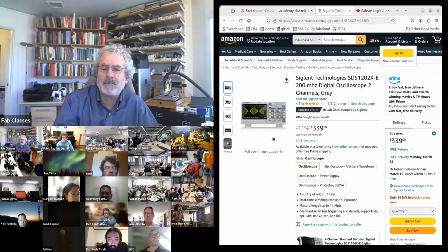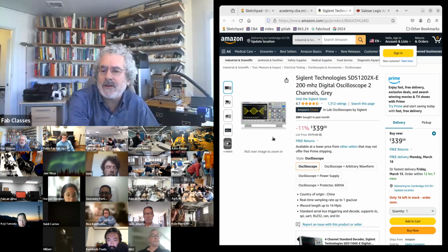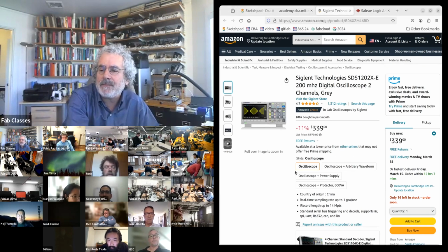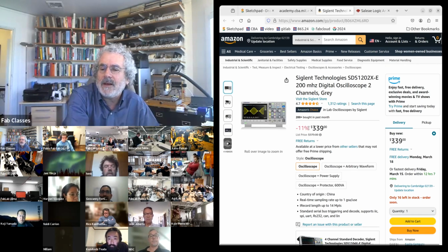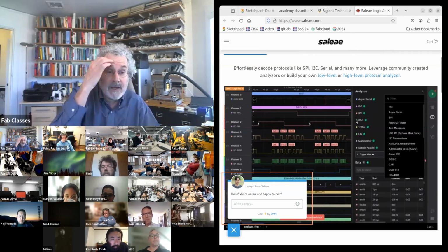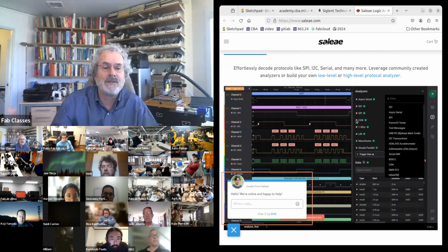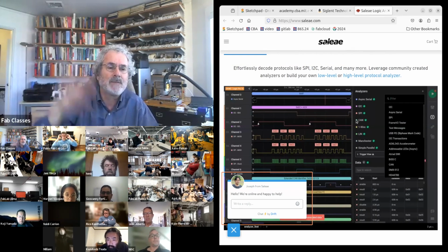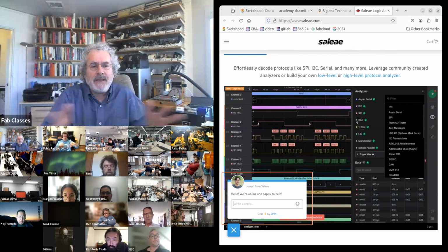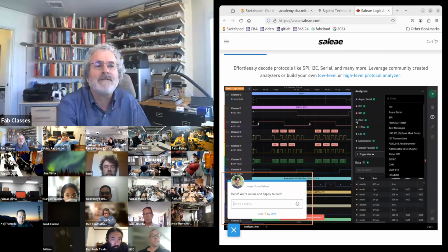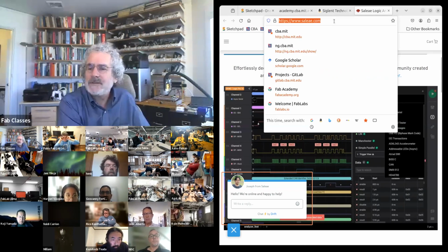And so, for example, for I2C or for serial, it can actually analyze them and interpret them. Then this is a powerful tool that takes the digital signals, runs on your computer, and it knows all of the protocols, and it can take big data traces and can find what's happening in them. And there are a number of very inexpensive knockoffs of those.